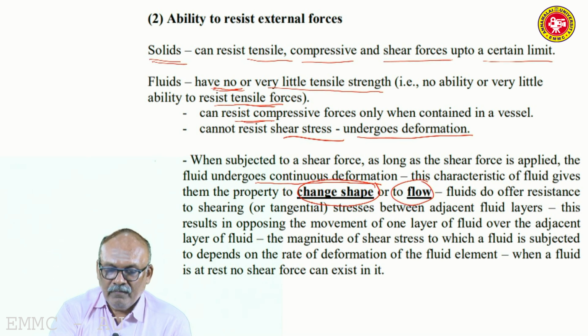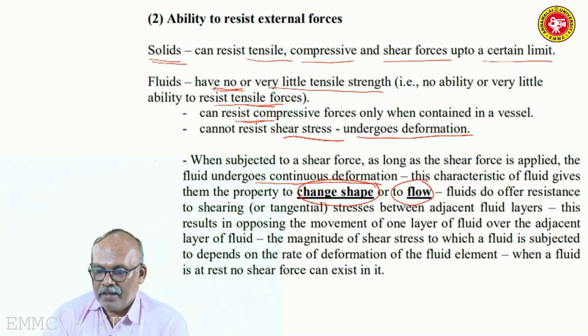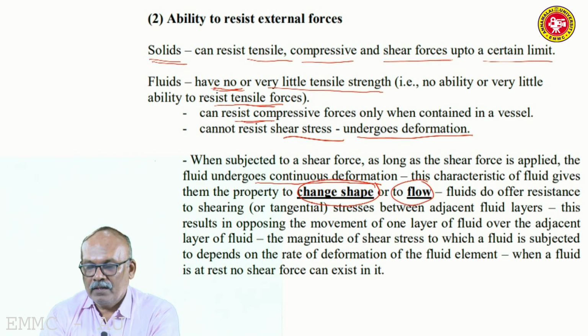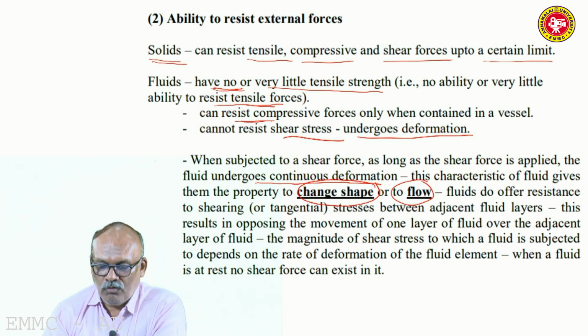So the fluid, whether it is a liquid or a gas, cannot resist any form of shear stress. When you apply a shear force to a fluid, it undergoes deformation, and as long as the shear force continues to act, the fluid will undergo continuous deformation, and this characteristic of a fluid gives the property to change shape or to flow.